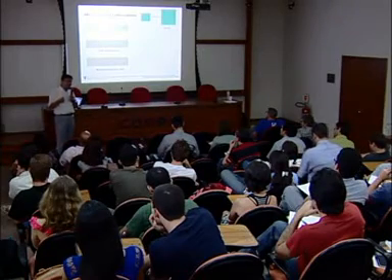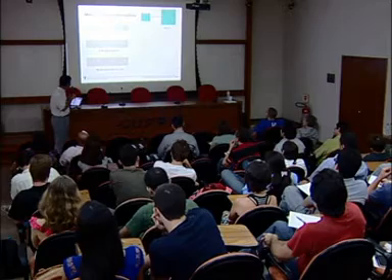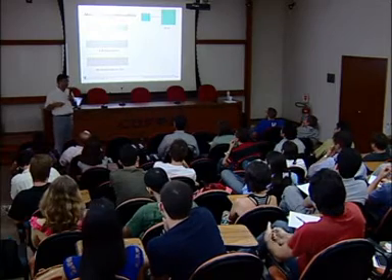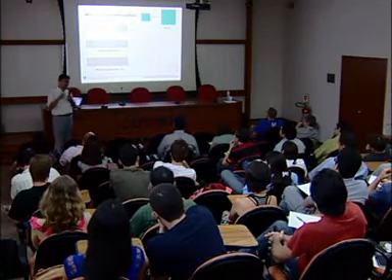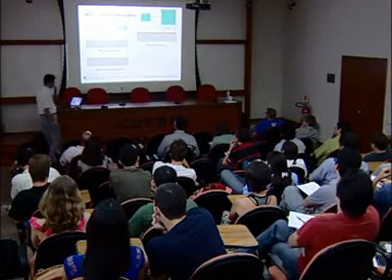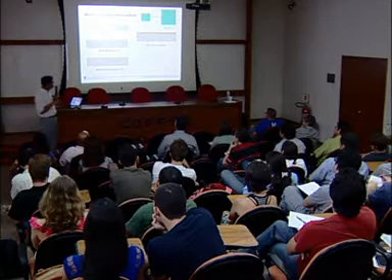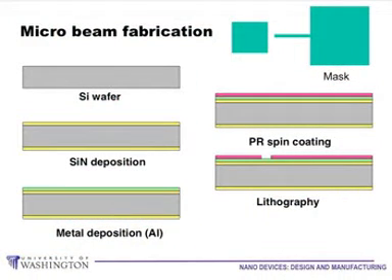So in MEMS structures, sometimes we need to actuate the cantilevers. Then there are various mechanisms for actuation, and one of them is electrostatic actuation. It's simple. We apply an electric potential like 100 volts. Then by the electrostatic attraction, we can actuate the cantilevers. That's why we deposited a metal layer on top. And we will spin coat a photoresist because we want to transfer this pattern onto silicon wafers.